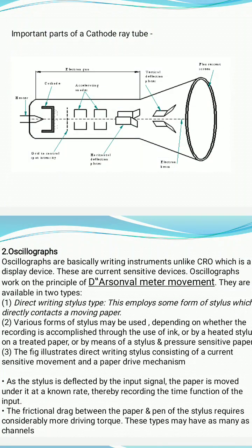So the XY plotter has a plate having two beams, one x-axis beam and the other y-axis beam, and these beams have a pen at the bottom side which moves on the paper which is fixed at the bottom plate. When the output signal from the primary transducer is supplied, the beams move and they form the images or the graphs with the help of the pen on the paper.